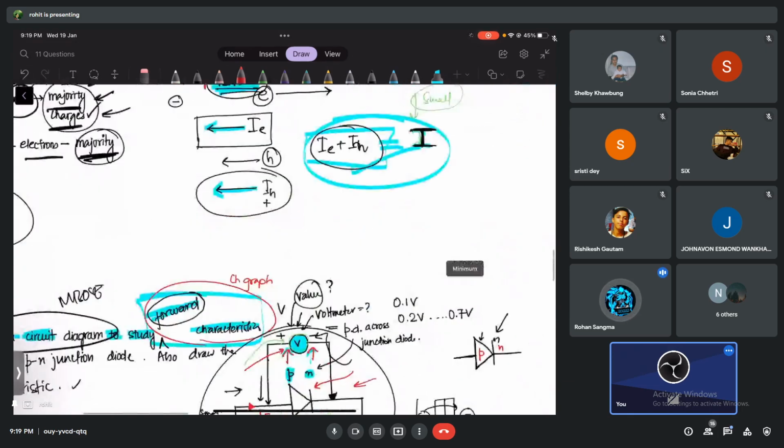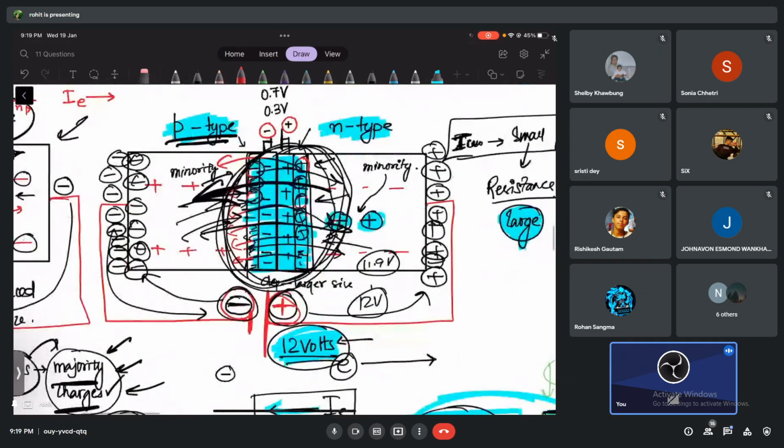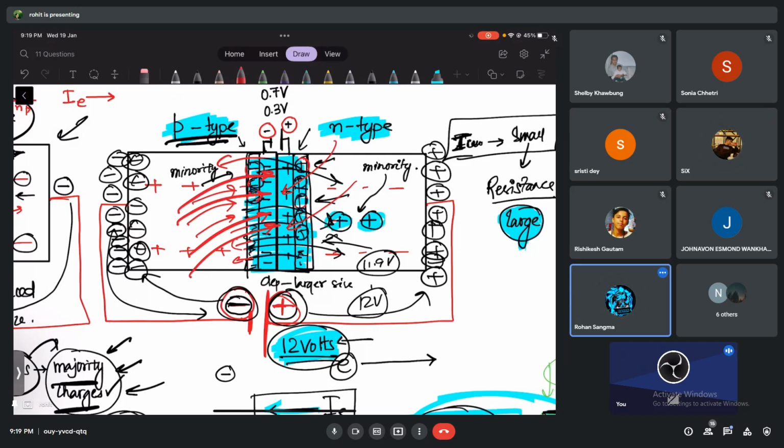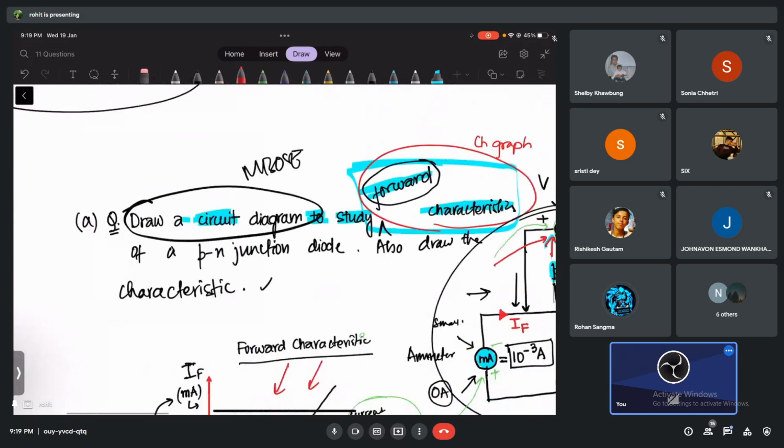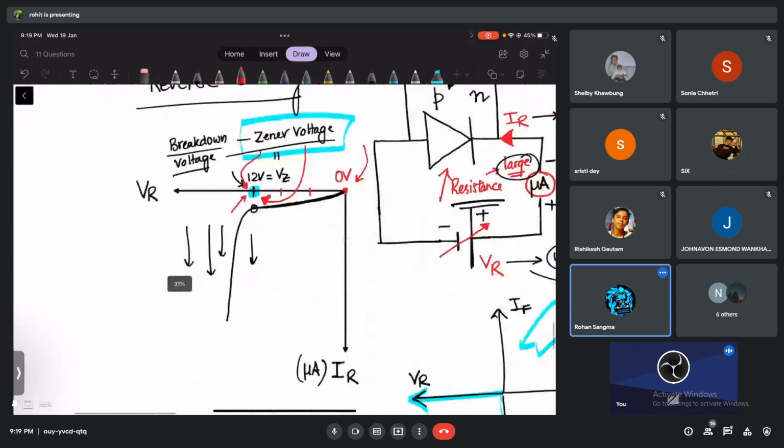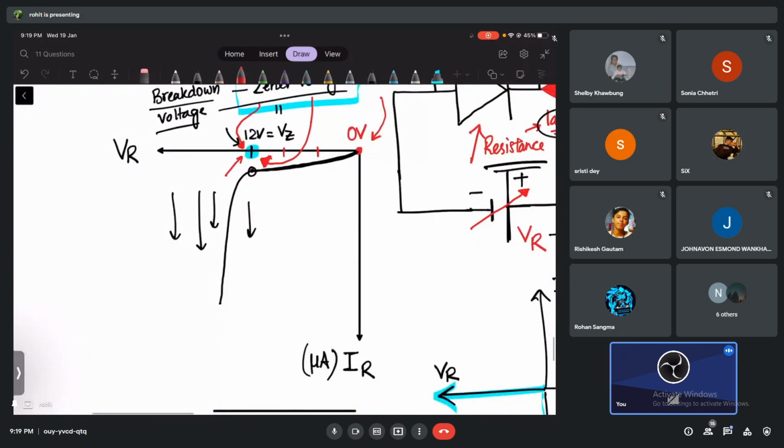Current rises rapidly, but why does it rise rapidly? Because the bonds in which junction? In the depletion layer, the bonds, are they still intact or do they start breaking? They start breaking, and what happens after that? The charges become free, and now will you get a very large reverse current now? Very large reverse current.